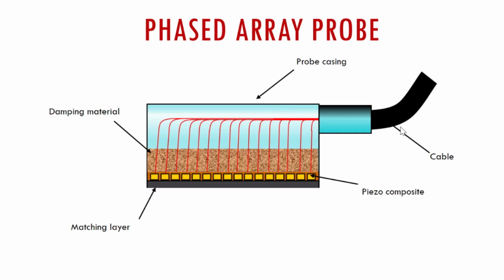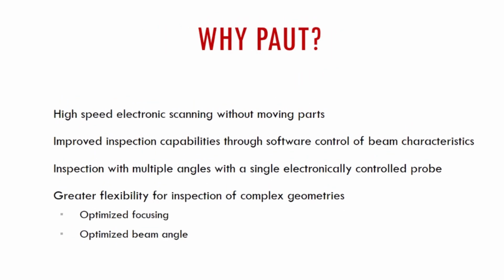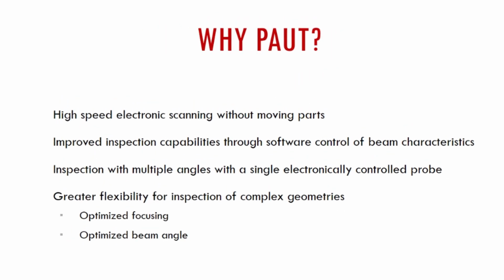These are all the crystals. This is the damping material. This is the probe casing, cable. This piezoelectric material is made up of piezo composite. Why PAUT? It has high speed electronic scanning without moving the probe and improved inspection capability through software control of beam characteristics. Inspection with multiple angles.